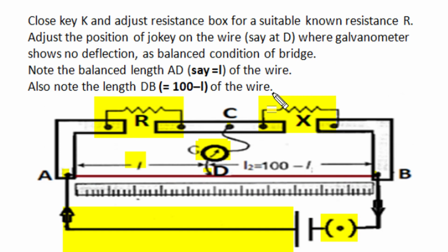Now this condition is known as the balance condition of the bridge, and in this balanced meter bridge condition, this length of jockey position from A is known as the balance length, and let it be L. So the remaining length of wire, if L is in centimeter, is 100 minus L centimeter.